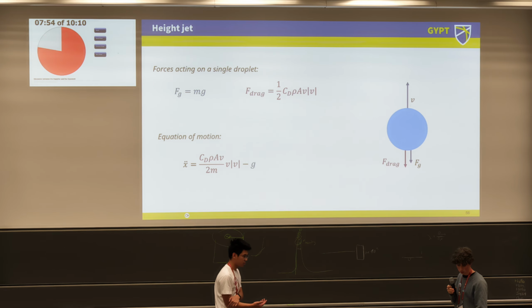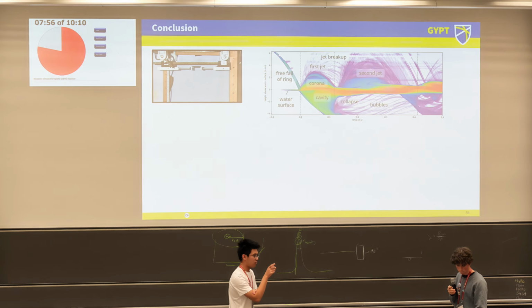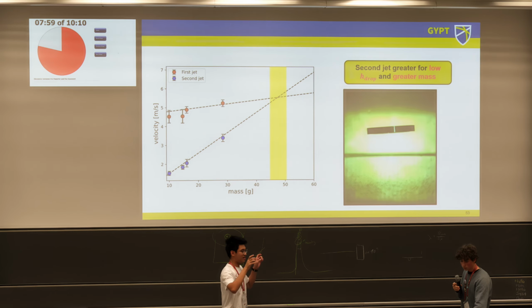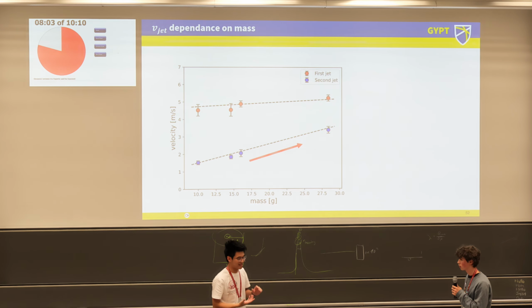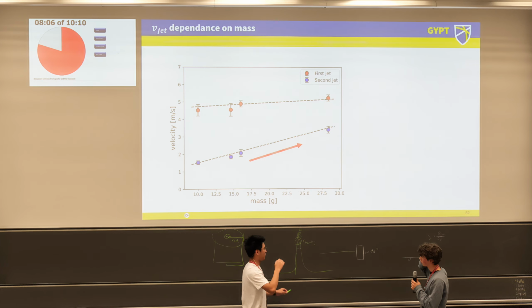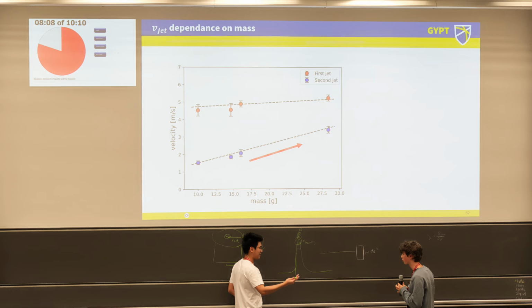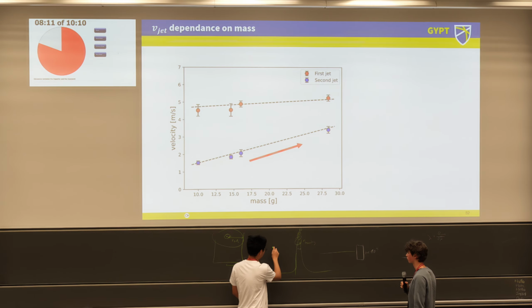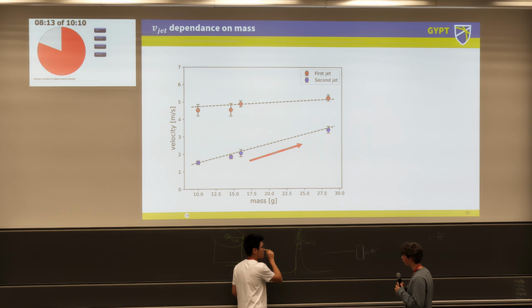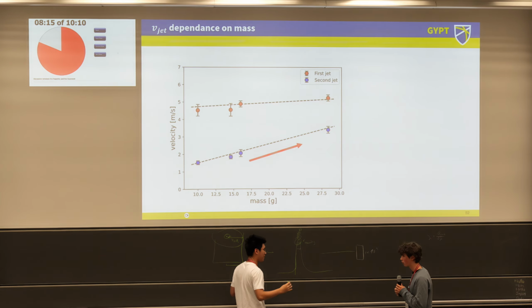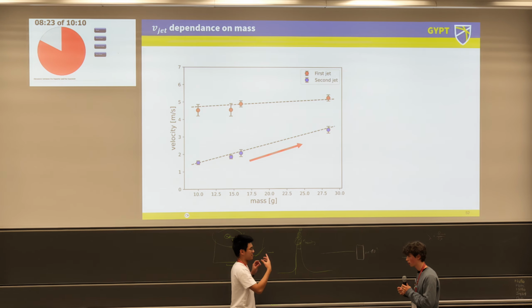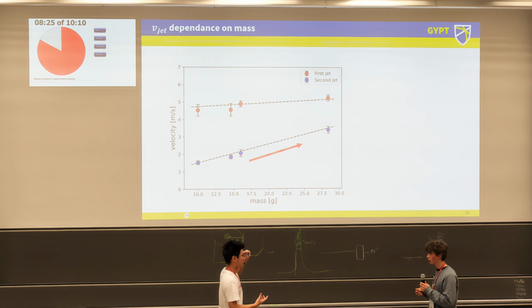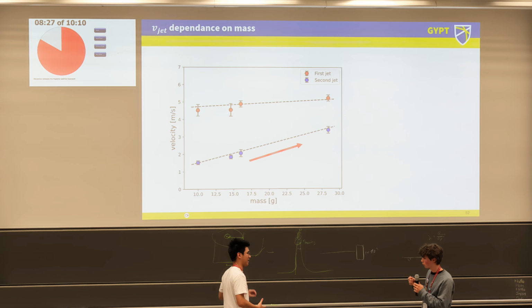However, I would suggest the reporter actually calculate the added mass from the water that is going to be pushed down, and that is more important because that is important when you also model the second jet. We believe that it's kind of missing in the analysis. One way of approximating the second jet from the first jet is that you have the added mass, and then you calculate the radial flow of the water in the middle, and you apply the geometric focusing factor, and then you can find the second jet height. So we believe that would be a lot better, because you can actually model the dropping velocity of the ring. Well, I agree.